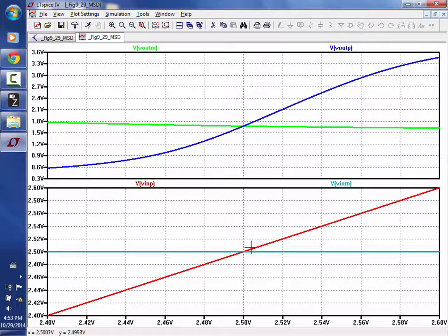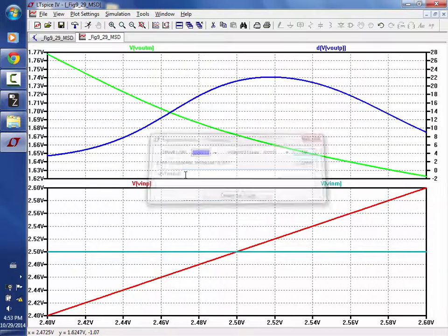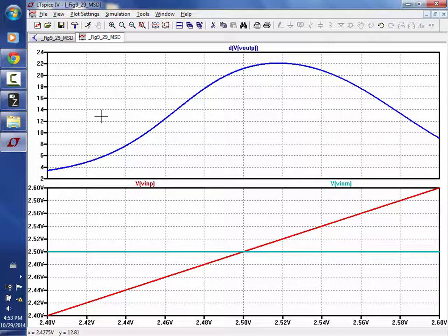So if I look at, say, right around here, the input wiggling back and forth, what kind of wiggle do I get out? That's the gain. How do I plot that? Yeah, I take the derivative of the output. The output is only like 22. And you go, wait a sec, can you really design a data converter with an op amp that has a gain of 22?